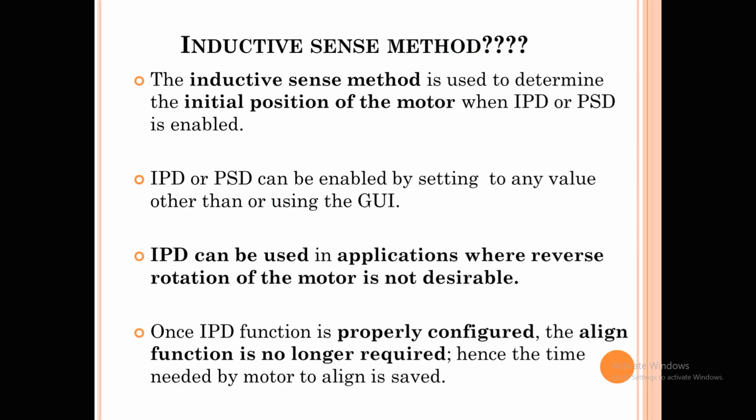So the next startup method is the PSD method. PSD or IPD, both are the same term: initial position detection, or position state detection. Both are the same thing, just different companies utilizing different names, so more or less the concept is the same. First, how does PSD or IPD work? It utilizes inductive sensing methods. The inductive sensing method is used to determine the initial position of the motor.